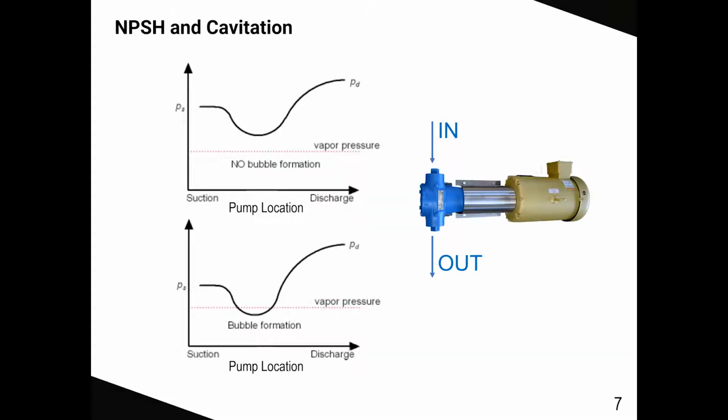In a fuel oil system operating in a vacuum condition on the suction side of a pump, we end up with an elevated vapor pressure line, which facilitates cavitation in an improperly designed system.